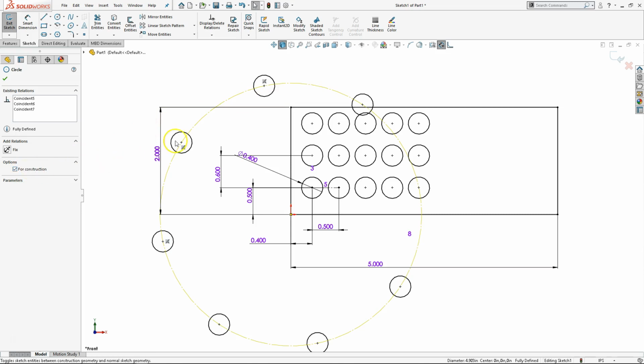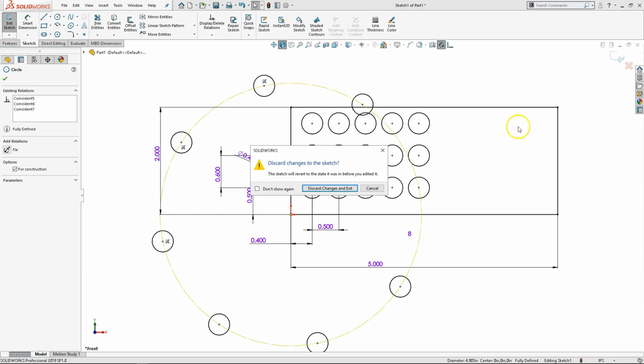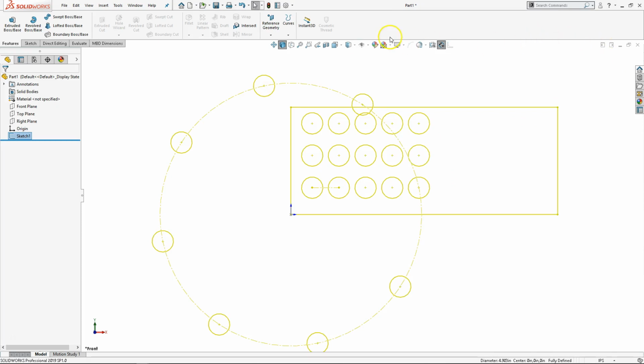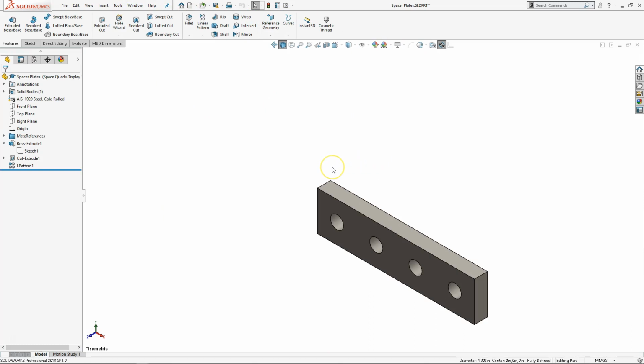All right, so when you're creating this geometry, and this is going up into higher complexity than the assignment, these are some of the little tricks and traps that you're going to run into in using those patterns. All right, so going back to the spacer plate, I use a pattern. So one path is to reuse, repurpose. I draw the 1 by 1, and then I save it as the 2 by 2, and then I save the 2 by 2 as the 3 by 3, and I build up through those patterns. The other option is to use configuration, and each one has its pluses and minuses in the complexity of the geometry.